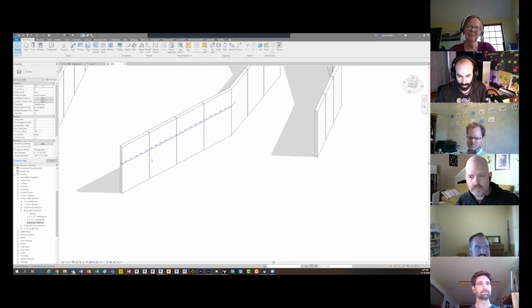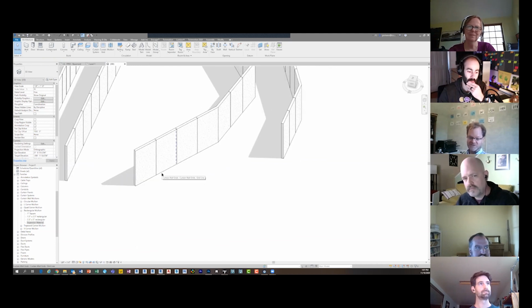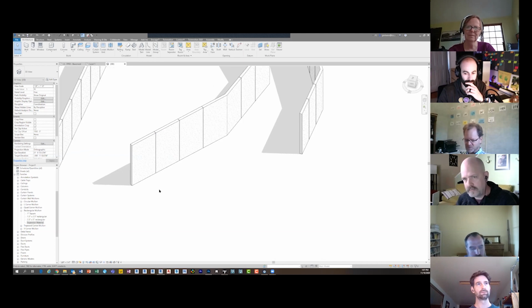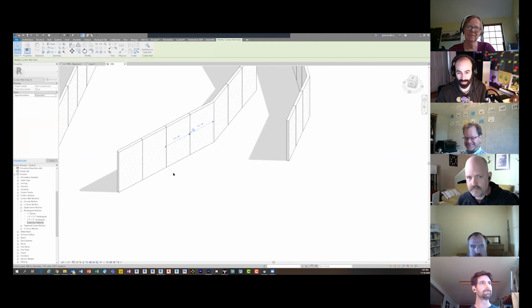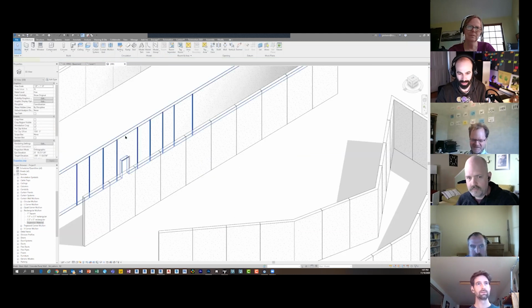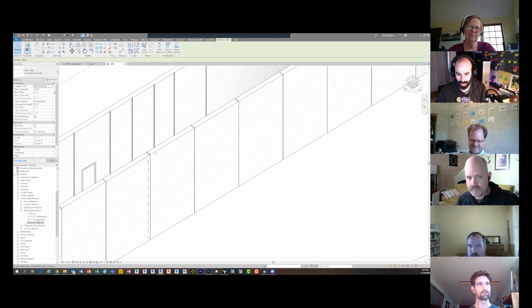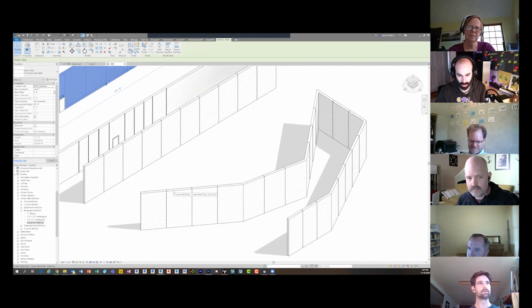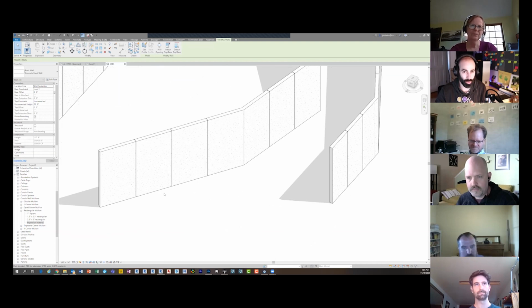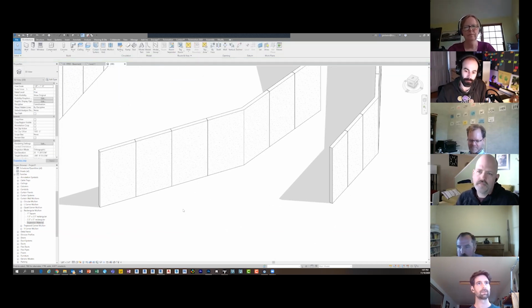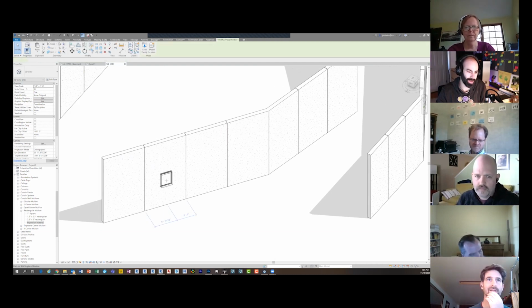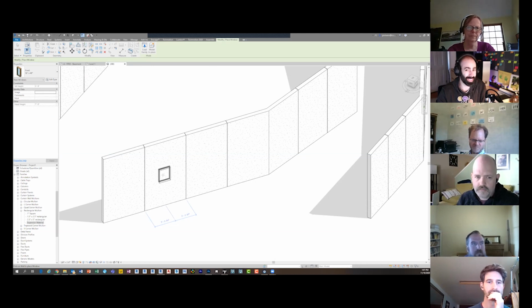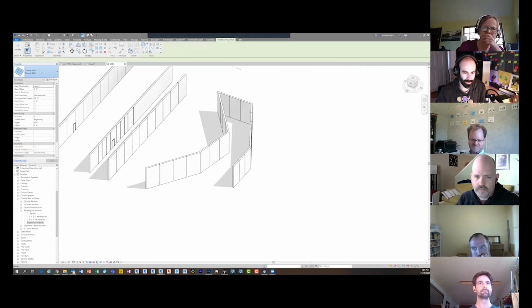What happens when you want to put, let's say, a door in between the two panels? Is that going to clean up okay, or is that going to be something custom that has to be done? No. So right, this is the downfall. So this is a wall. This is a curtain wall. Okay, curtain walls, right? There's only certain ways that you can put doors in them. And so when it comes to putting a door in this, you're going to run into a few issues. Although I will show you that because these are walls, it's unique. So when you draw a storefront, it's pretty wild.